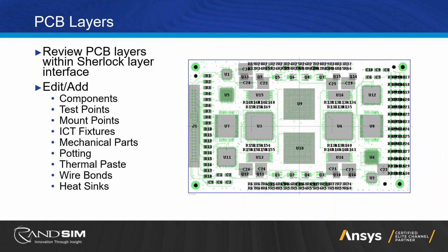The first thing that you're going to do once you're in Ansys Sherlock is import in your design. When you are doing your layout in whatever layout tool you specifically use, two common import types for Ansys Sherlock are the ODB++ and the IPC-2581. There are some additional ones as well. If you're curious about some of the other import options, let's have a discussion about that at another time. But the most common one that we see is the ODB++.